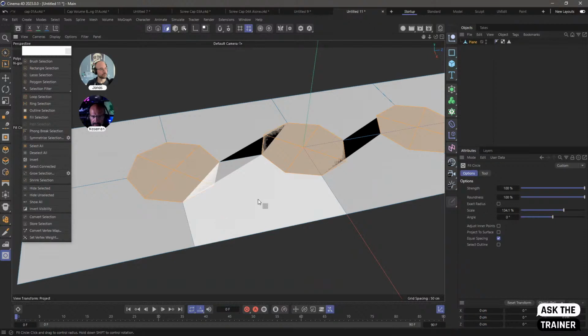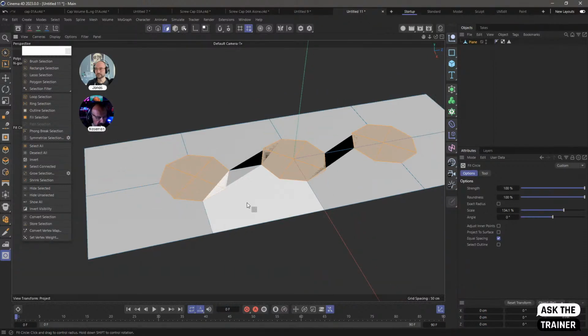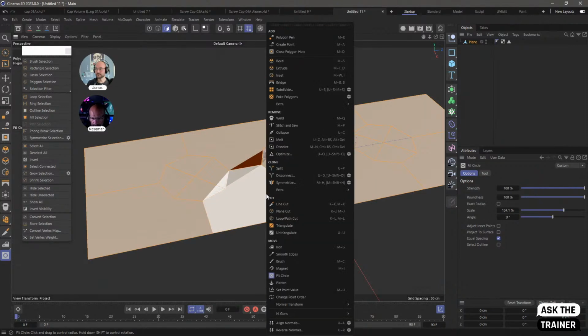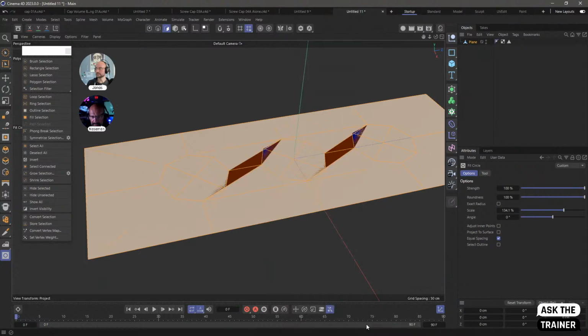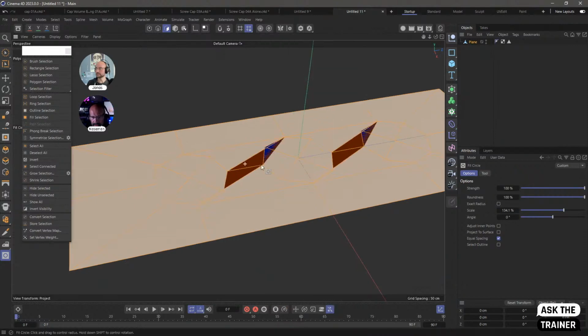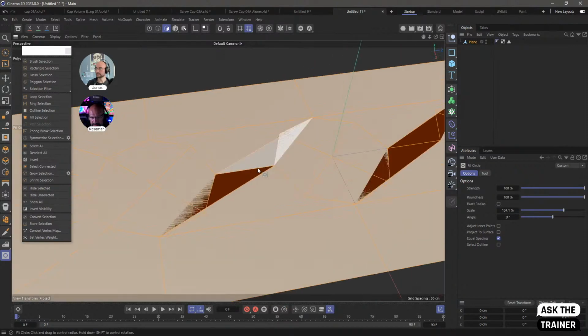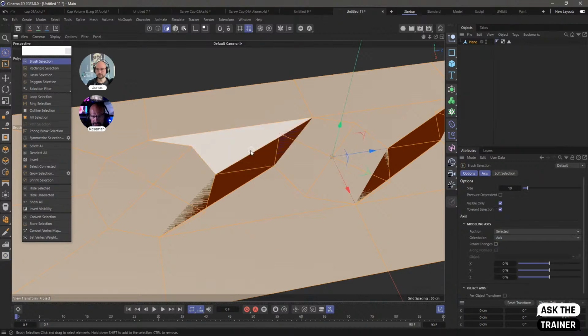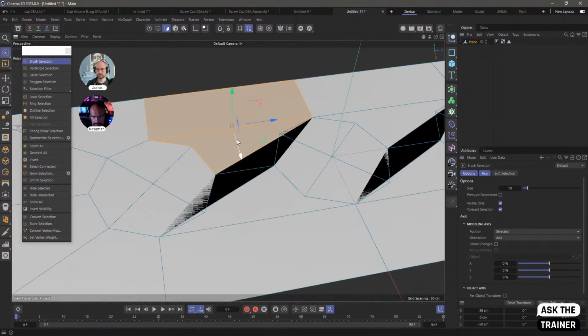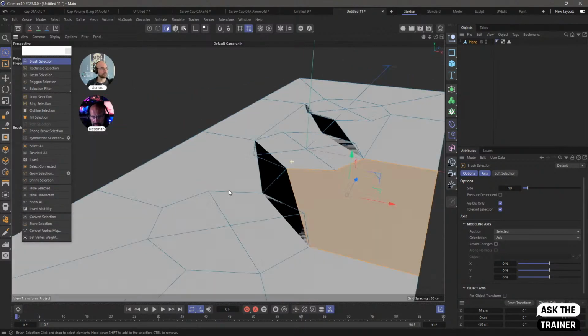The strategy needs to be compatible with your way of working. So you can always select everything, right click, and remove n-gons. This is going to triangulate things so you can identify various issues if they are present. But it doesn't matter that much because as you move forward, you'll be able to patch things up using your selections, your polygons, and all that nice stuff.